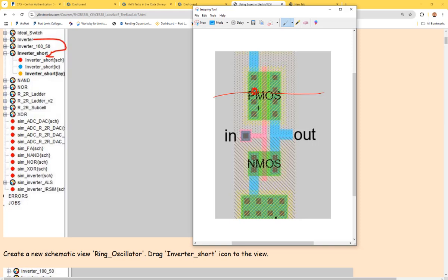Via 1 is a through hole that directly connects to metal 1. Remember, when you place a transistor over here, the vias already exist. You cannot get rid of vias. So even though you don't have a metal 1 wire on it, these vias are metal 1 vias, or probably not directly metal 1, but the via, usually aluminum, in the middle, directly shorted to metal 1. So if you run the metal 1 on top of the via, they are connected. So you are basically connecting to the P plus of the transistor.